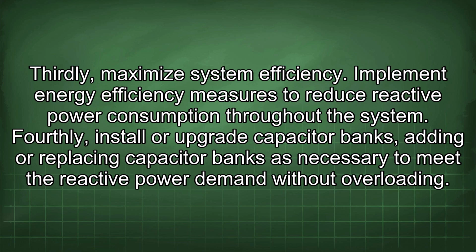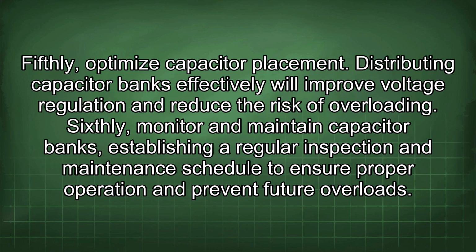Fourthly, install or upgrade capacitor banks, adding or replacing capacitor banks as necessary to meet the reactive power demand without overloading. Fifthly, optimize capacitor placement. Distributing capacitor banks effectively will improve voltage regulation and reduce the risk of overloading.